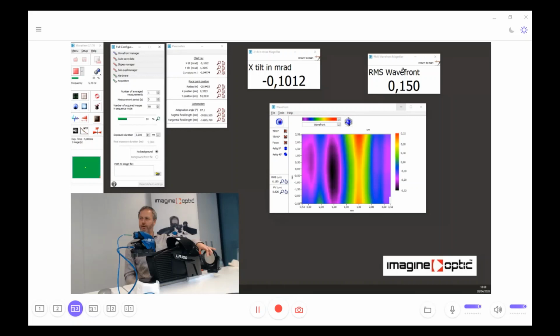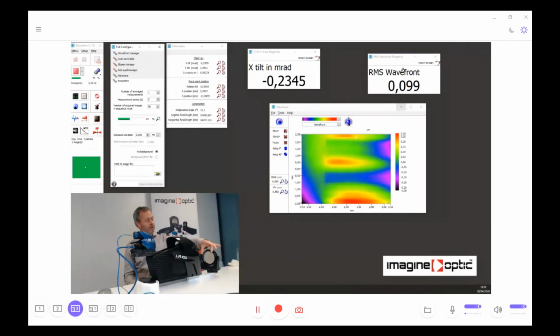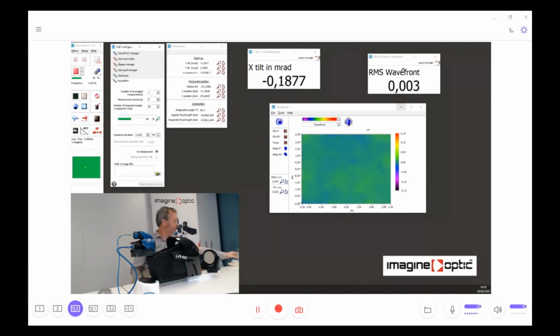So it's very important to know what kind of thickness inhomogeneity is in this kind of lens, this kind of glass, to check that this glass can be used for purposes other than just a window. As you've seen, we did many measurements here. We still have 3 nanometers per meter square wavefront error. And we can do many kinds of things by doing this.